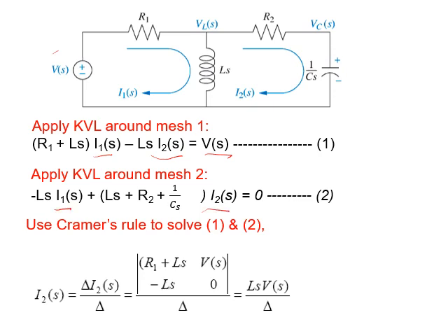When I am in loop 2, I1 is the other current, so I will consider it with a minus sign, minus I1 multiplied into the impedance in between the two loops, which is LS. That's what's shown here. L minus LS into I1 plus, since I am in loop 2, calculating for I2, the sign will be plus. So plus the total impedances in loop 2 multiplied into I2.